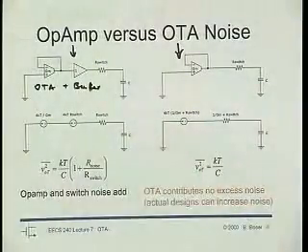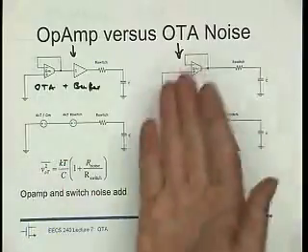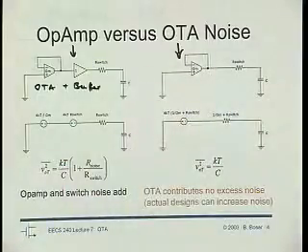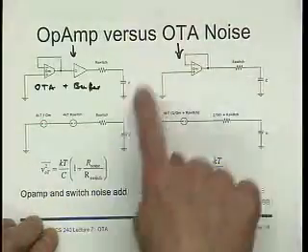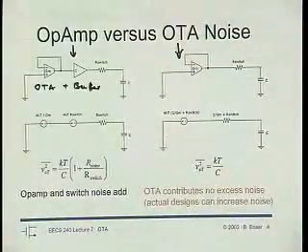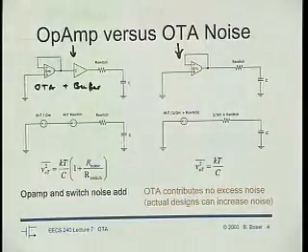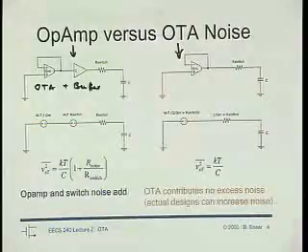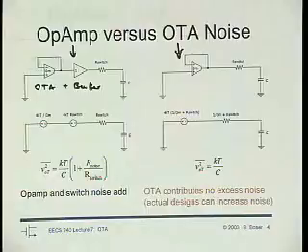Another difference was noise, because we have a simpler system here, so we also get less noise. Hidden in this very simple picture is the rather profound observation that the kT/C noise and the noise from the operational amplifier do not somehow add up. They're one and the same. There is no distinction between them, and that is very helpful. It somewhat simplifies design and analysis, but it also precludes us from guessing possibly wrong noises.